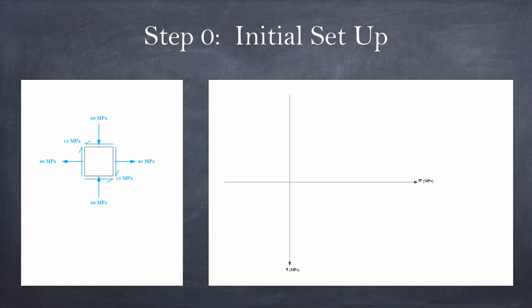Before we begin the calculation, I will start off with the initial setup, which I tend to call step 0, because it's before question 1 or 2 or 3. It is something that every time we do Mohr's circle, we should begin here. First, we set up the axis. As I already said, for this method, we set up shear stress downward positive, right? Because the question gives units in megapascal, the distance we measure here is in megapascal as well.